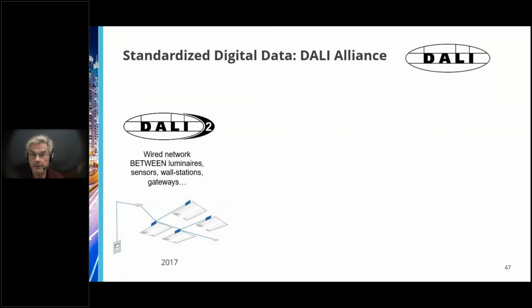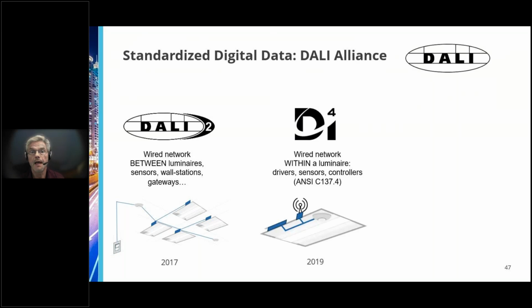In 2019, the D4I protocol for communication between components within a single luminaire was adopted in North America as the ANSI C137.4 standard. LED drivers that support ANSI C137.4 communicate digitally with sensors and controllers and use North American power supply voltages.